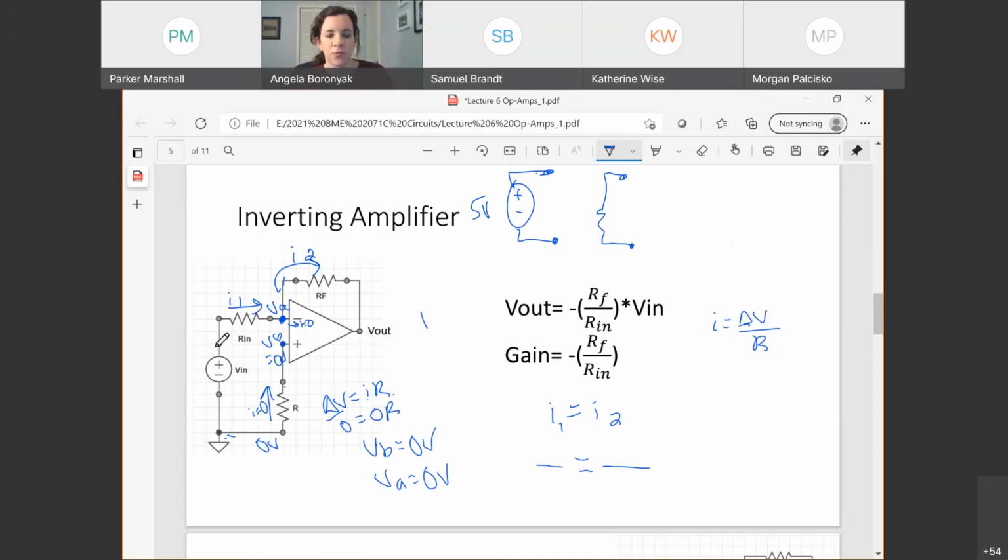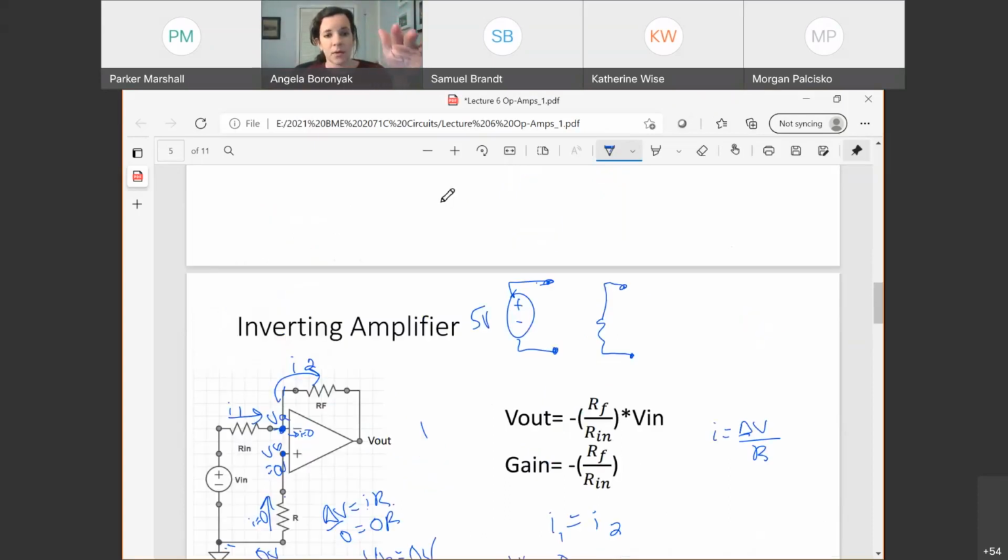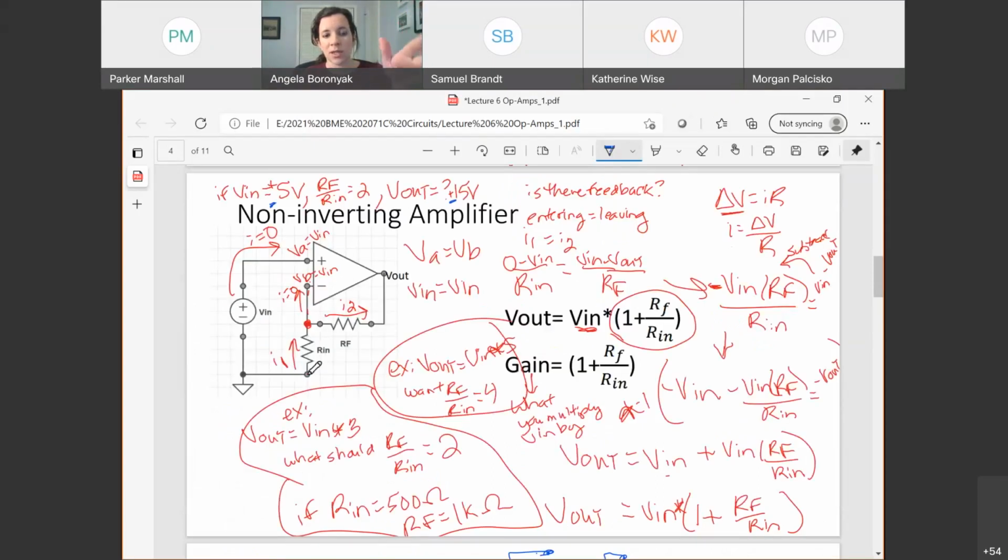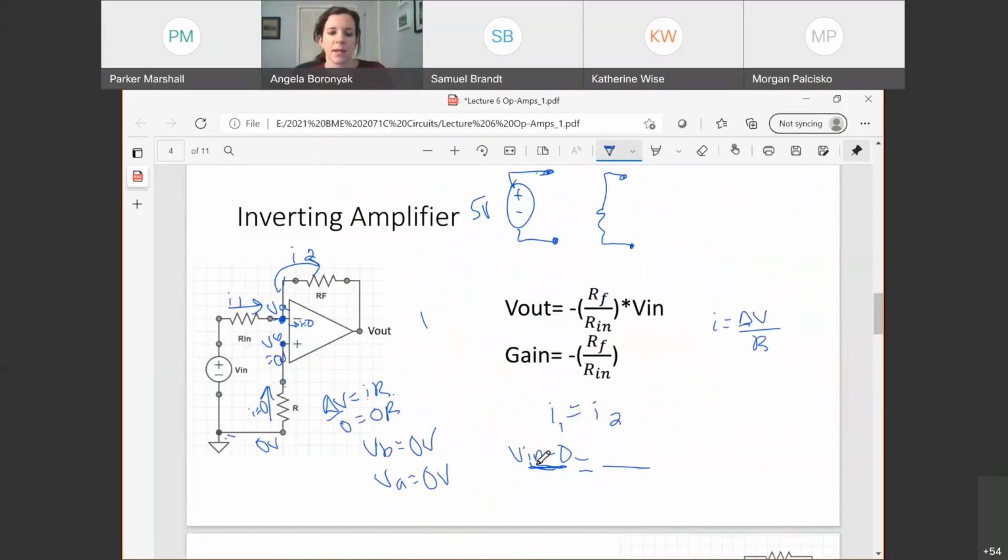Yeah, so he goes from Vn on this side to, what's my voltage at VA? 0. Or you can just write V in here, but I like to always write the 0 so I know which way it is. Again, when we did it this way, with this circuit, then I started at 0, and so it made us have a negative sign. If I get lazy in that, then I can often miss my signs.